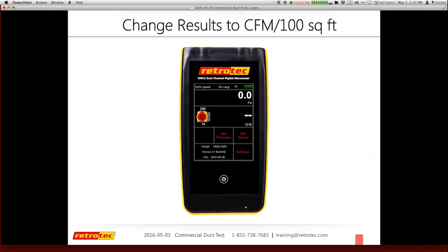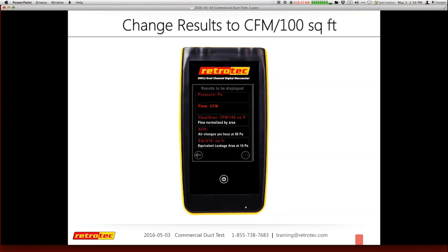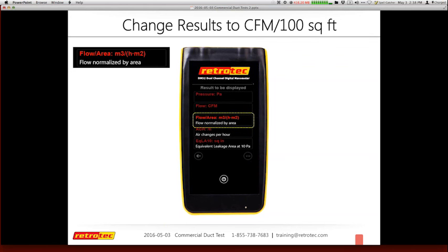I've got a quick slide that goes through commercial for those people that live in residential and are thinking about how commercial works. Commercial lives in, again, inches of water column versus pascals. So I thought I would throw out some numbers so people could see that 25 pascals is 0.1 inches of water column. 500 pascals, which many residential people think is a high pressure, is only 2 inches of water column. And when we get to 2,000 pascals, we're still only approaching 8 inches of water column. So my goal is to put that in perspective for the residential viewers out there.